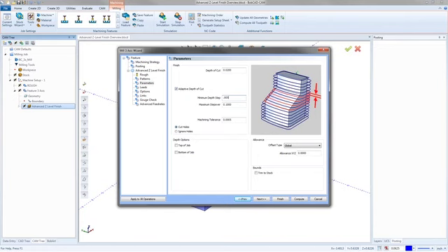I'm not going to compute this because that'll take a lot longer to calculate. But basically, it's going to go in and find the areas where a 5 thou depth of cut could give them a much better finish. And it's going to add all the toolpath it needs right there. Again, within the 5 thou range. It's the same thing you run into when you're running 20 thou. It's got to go a distance, so it's a depth. So if this is 0, the first pass doesn't happen until 20 thousandths. Then 40, 60, 80, 100.